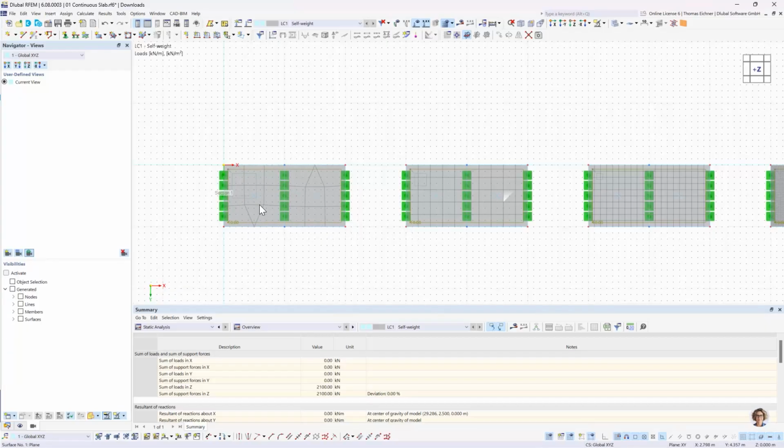And we also see we even have here a triangular element, which is also not perfect, since it's just better to have a uniformly distributed rectangular element mesh. Sometimes it's not possible to evade those triangular shapes, but if possible, you should try to avoid them.